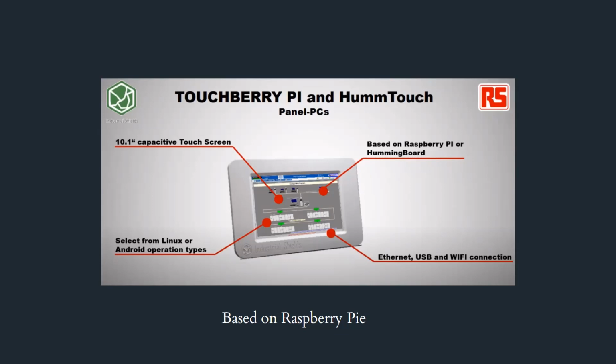The network traffic will increase if we continuously send a high amount of data in the communication link to the local server, and therefore the connection will get slow in the environment. So we need to produce less network traffic, and we need to do our communication efficiently using the wireless medium. Therefore we only send the important data in certain applications. That is why we do the computation at the sensor level. We send only the data that is necessary.